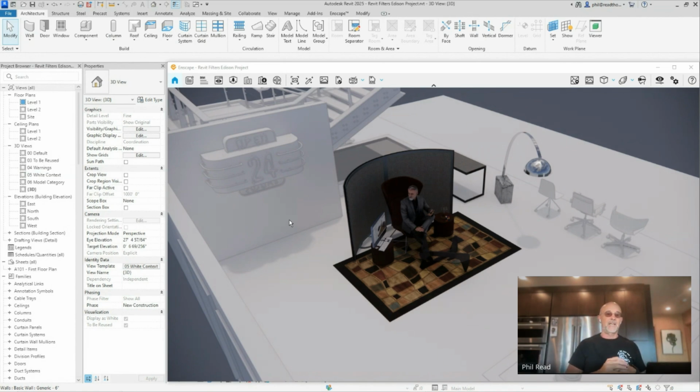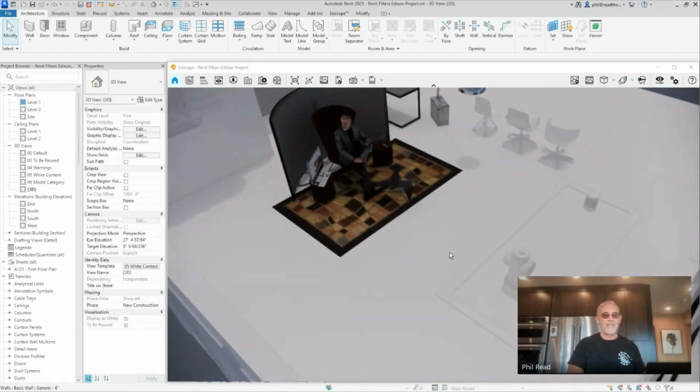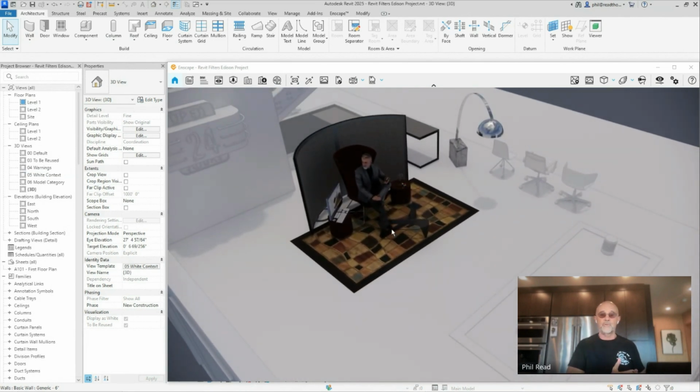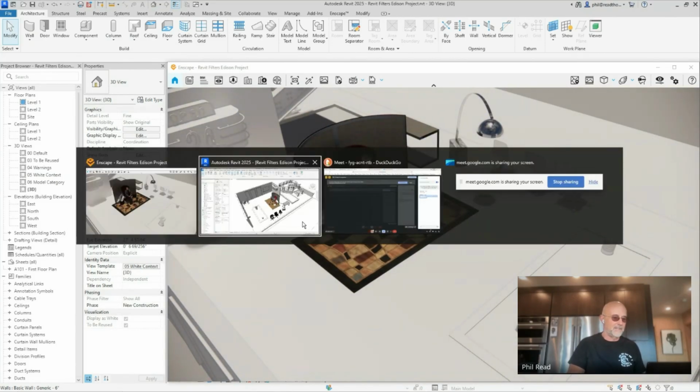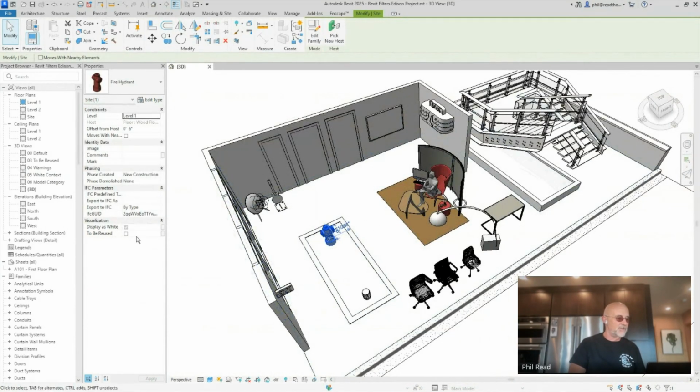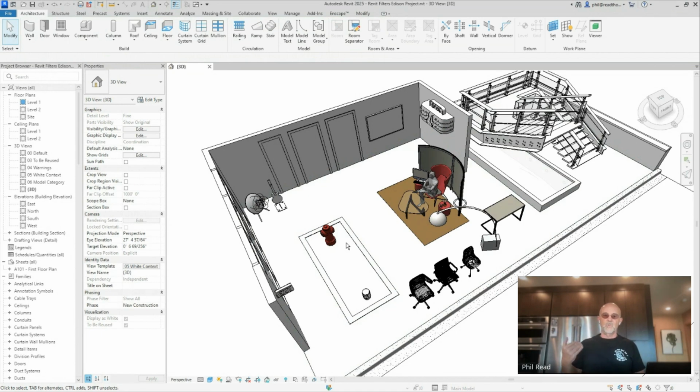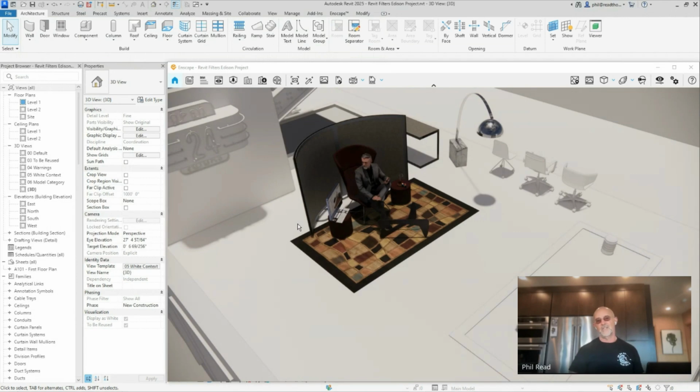This allowed them to say, I want everything in the model to be white, just de-emphasized, but certain aspects of it we want to highlight, and then we walk through live so that the client can focus on just that design issue. Again, it's a simple instance parameter. You select display as white, no or yes, and when you do that, it removes the white override material. So it's actually removing a material and then showing the real world value. It's a nice rendering hack, but it's also this idea that you can turn everything white except for the things that you need to focus on.